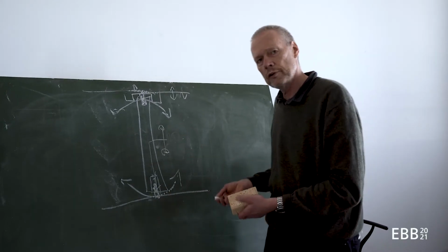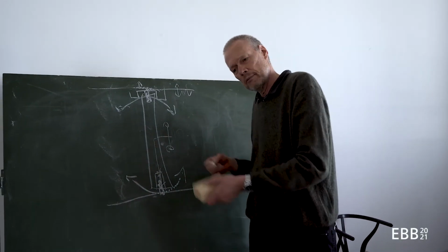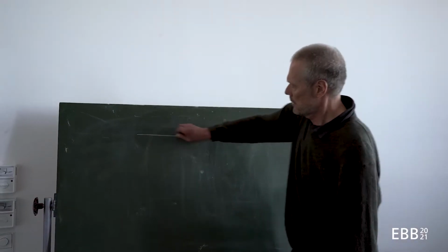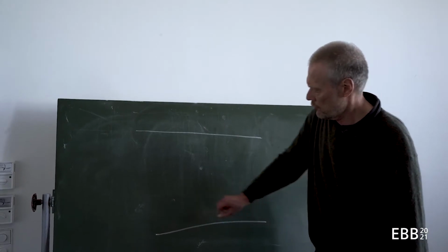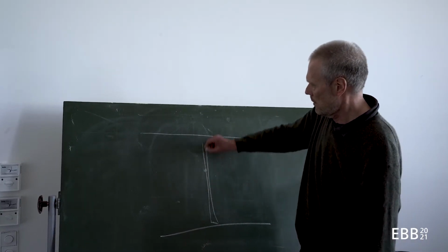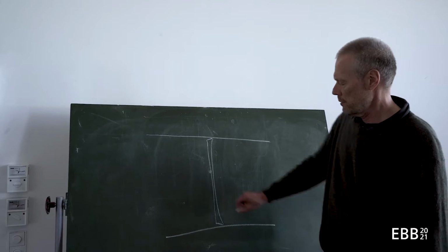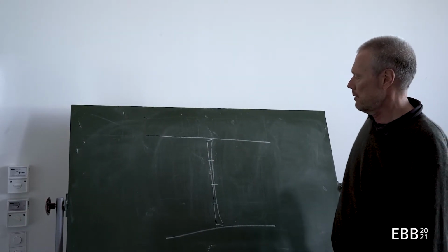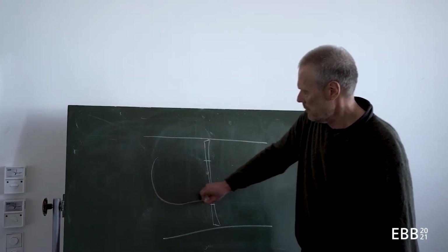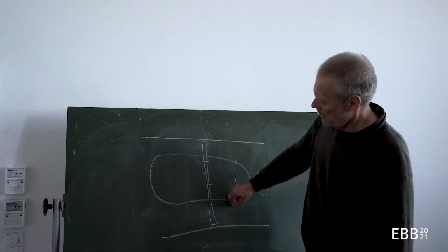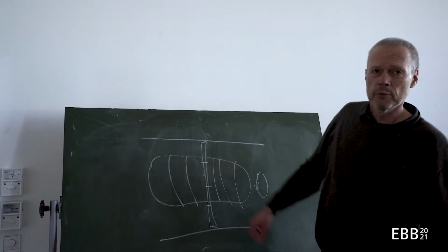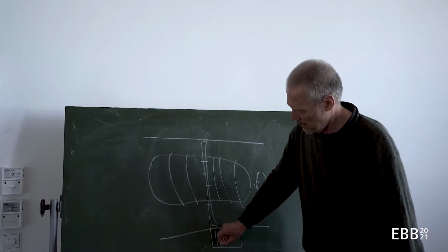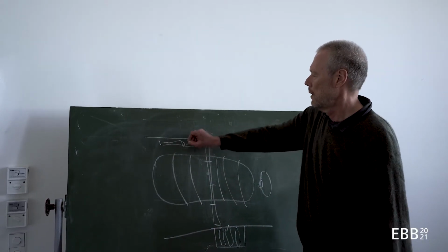And if I want to move the wall, I have to move them up again, and then I can slide a wall. I have a space that should be subdivided with these moving walls, so they have to be separated in elements. And if I want to use this, for example, as one big lecture hall, these elements have to be stored someplace, and this can be done either in a niche or alongside a wall.